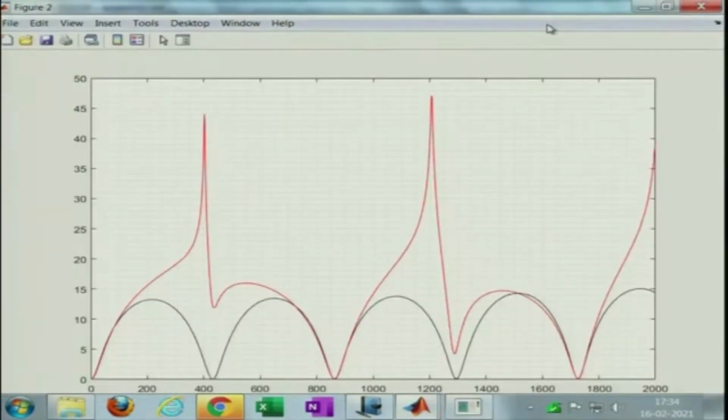Before we start putting in extension at the outlet, there are quite a few things I want to discuss. You see, let us first put the data tip. Okay. So, forget about the peak, it can be anything, theoretically it is going to infinity. So, I do not really care about the amount of attenuation that is produced. The frequency at which it is happening is important. We are doing the discrete frequency at 11 hertz.